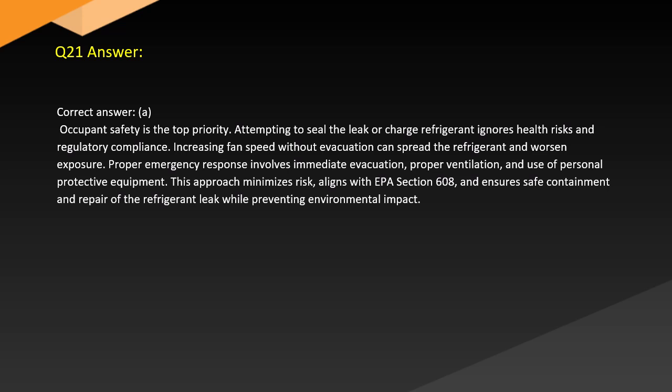Answer. Correct answer. A. Occupant safety is the top priority. Attempting to seal the leak or charge refrigerant ignores health risks and regulatory compliance. Increasing fan speed without evacuation can spread the refrigerant and worsen exposure. Proper emergency response involves immediate evacuation, proper ventilation, and use of personal protective equipment. This approach minimizes risk, aligns with EPA Section 608, and supports safe containment and repair of the refrigerant leak while preventing environmental impact.